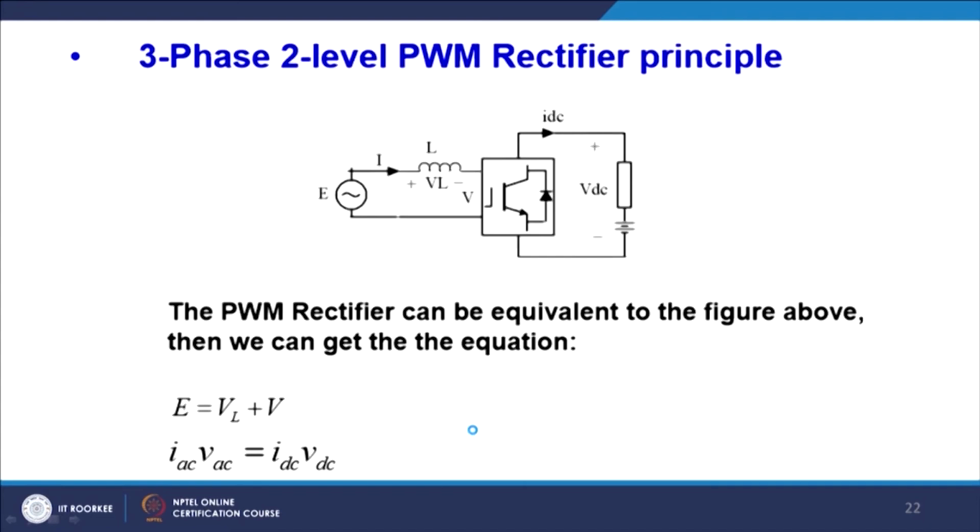So, how does it work? This is the single line diagram. Generally, this is for the battery charging application. We want to charge our battery at unity power factor. Then this will be an inductor, and this is the IGBT, which can be operated, for lower power ratings, at as high as 20 kilohertz. I will show a little data on it.